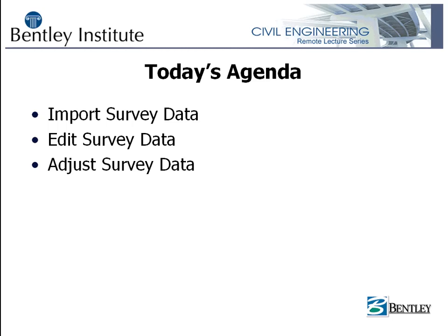So the first thing I'm going to do today is set my screen up like I have it on my desk for InRoads. Then I'm going to go through a few new buttons and toggles that we've added to XM. And then we're going to go right into importing survey data. I'm going to import 2 or 3 different types of data. Then we're going to edit survey data using the survey codes. Then we're going to adjust data. I'm going to do 3 different adjustments, and hopefully that is what you would normally do if you used InRoads Survey.